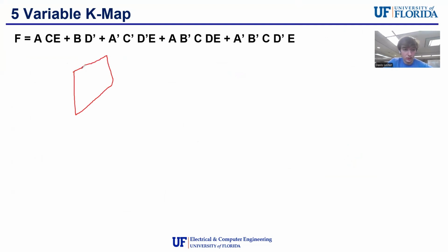So if I have a K-map here, right? K-map, let's draw some rows. This is like if I was looking down at my paper or something like that. So we have some 1, 0, 1, 0, etc., right? Oh, this is just a 4-variable, right? A 5-variable works by connecting this K-map across the 3rd dimension into another one. So we'll have K-map 2 right here. I guess that's a pretty bad drawing, but we'll have what's essentially like a cube of K-maps. So again, 1, 0, you get the gist, right?